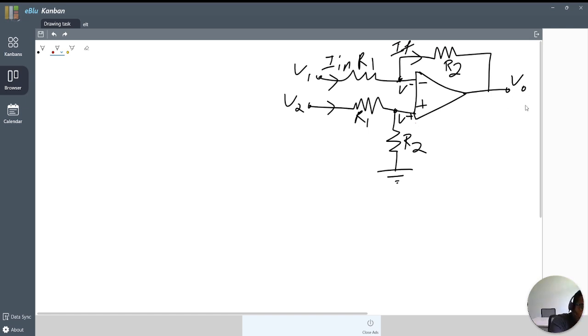So V out becomes, let the gain for this differential amplifier be K, so V2 minus V1. According to the rule of op-amp circuit analysis, V non-inverting equals V inverting. So our V non-inverting is a voltage divider through the plus signal, that is the non-inverting input.